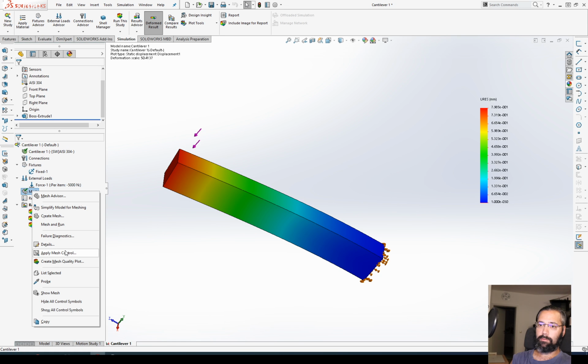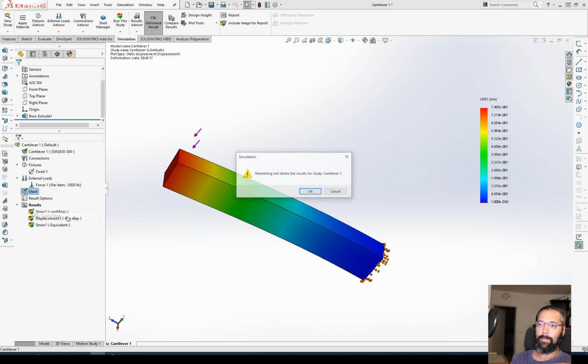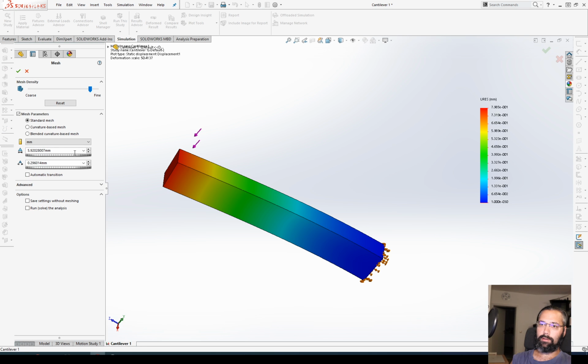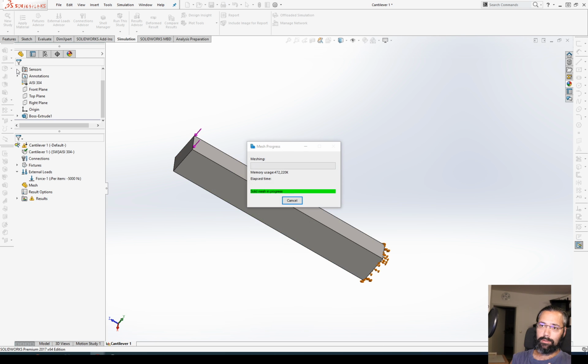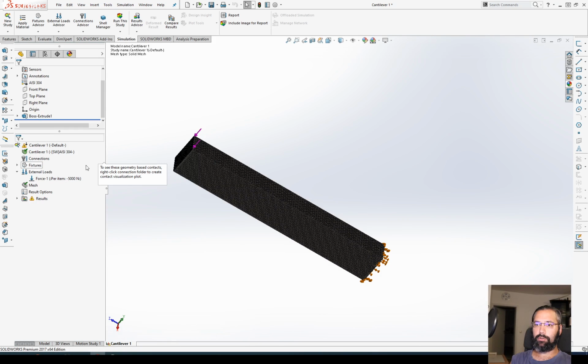Meshing, we can probably demonstrate that the mesh doesn't really affect the result. Basically, when you mesh, you want to use the largest mesh you can to get results that don't change when you change the mesh. Did that make sense? Tell me down below if I made sense. If not, I can explain it again.